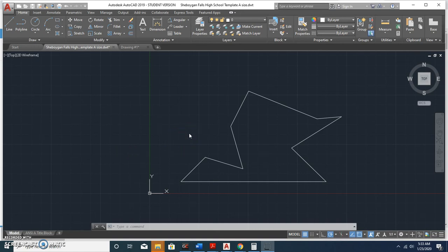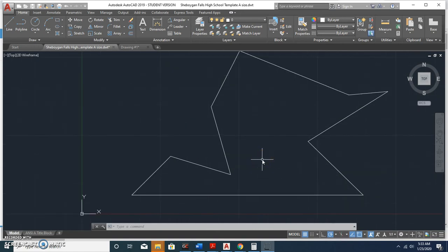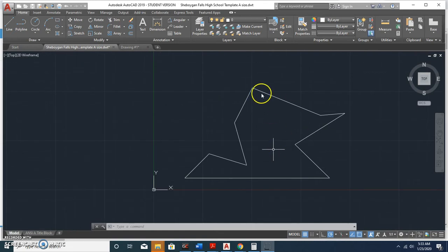Okay, now that you have all your object lines complete in your drawing, now we need to do what's called annotating the drawing. Annotating drawings means adding dimensions, notes, leaders, center lines, hidden lines, those kinds of things. So the first thing you're going to do is, in AutoCAD or CAD packages, we try to layer objects. So we layer different entities on their own specific layer.